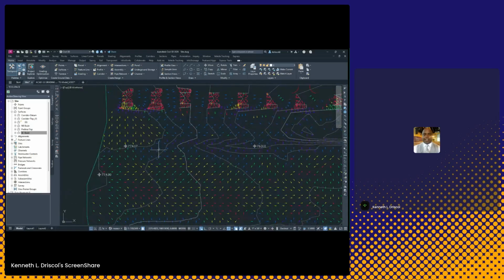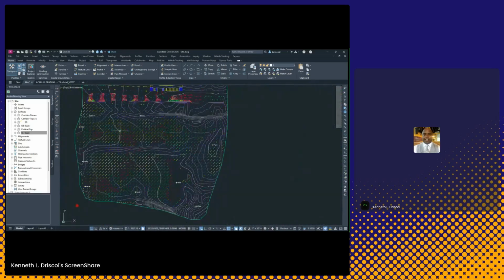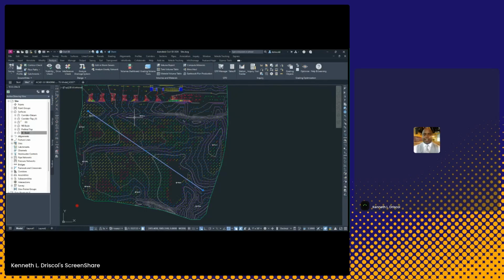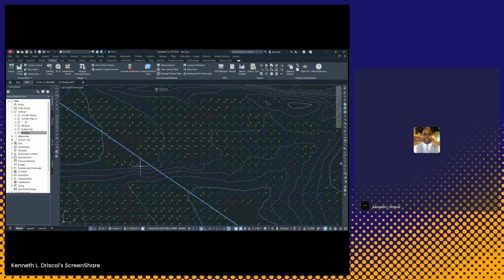But in reference to determining slope and flows, the simple thing that I will do at any time is put a polyline right through here. And if I pick on this and right click, there's a couple things that I can do. One is do a quick profile. So if I go a couple different places, we can do a quick profile. And then what do I want to understand in reference to the slope that's across here? So knowing this, I just have a polyline.